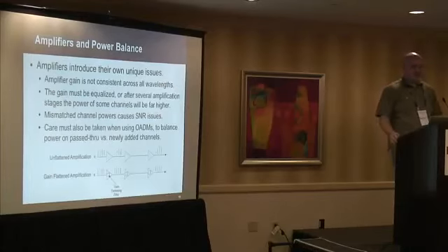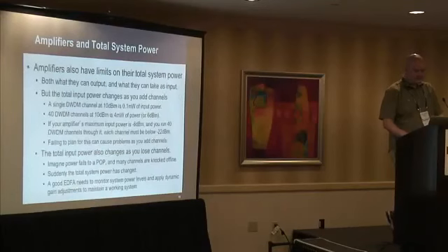What happens is the total power in the system can only be so much. The amplifier can only do so much, and so when you've got 10 channels and now you add 5 more channels, that changes the amplification that happens to each individual channel, and you need to flatten this out, so you'll have a lot of gain flattening amplifiers. This is what I was talking about.